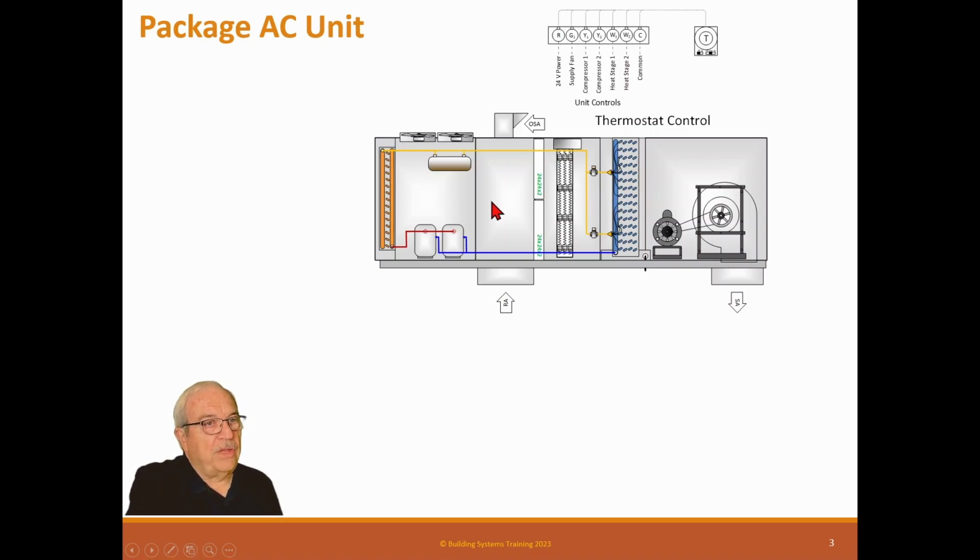If we didn't do that, then we would have to wait for the compressor to pump up this vapor to hot gas, and get the hot gas to the condenser coil and to the coil. So there's a lag, but with these solenoid valves, we don't have a lag. It's immediate. And these are the refrigerant circuits. Again, remember that I've shown the refrigerant section over here, but they can be anywhere. They can be beside the unit, on top of the unit, around the unit, you never know. So I've shown it just this way for clarity.